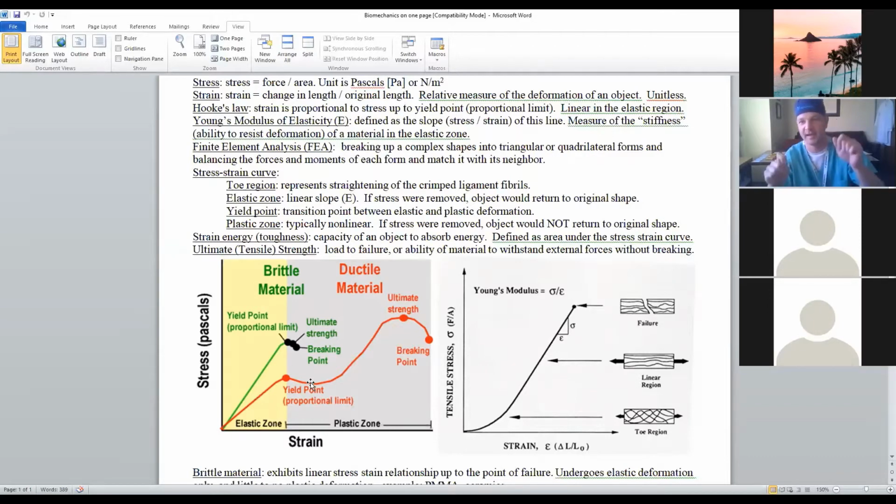So if you bend that knife, or if you bend that piece of metal to a certain amount and then let the stress off, it will recover some. It will recover the amount that it took to get to the yield point, but then the amount that it continues to be residually deformed, if you drew a line that's parallel to the elastic or to the linear version, that would get you back down to the strain axis. That's what its residual deformation is. And again, they've never asked that, but I think they possibly could.